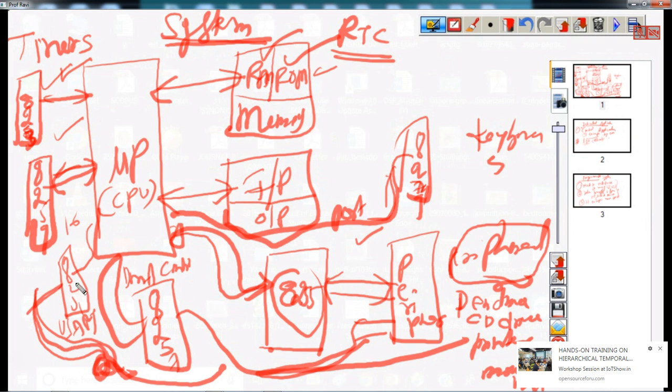If these things are available within the chip, your timer chip, your 8255, your 8251, your DMA controller, anyhow, that is not needed here, because here the only applications we need to perform are control applications, not logical or transfer applications. So there is no DMA. But all other things, like timers, and interrupts, devices need to be serviced. If we can find all these devices on a single silicon chip, then we get an advantage. So that is nothing but the microcontroller.